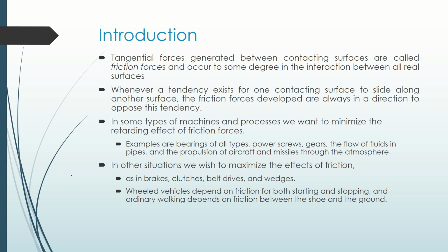As you all know, at a microscopic level, these surfaces come in contact over certain areas, such as irregularities of the surfaces, the peaks and the troughs that come in contact, and they interlock with each other. But because mg is acting downward, the entire force is not acting downward. There are certain tangential components acting on it, because when the two surfaces come in contact, for instance, one irregularity comes in contact this way, the other comes in contact and moves this way, the action reaction force is at a specific contact point or the tangent of the two curves, hence tangential forces.